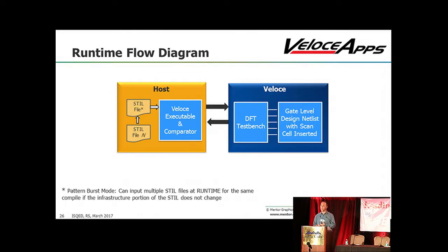You can run multiple patterns, just like you do on a tester. If you've got 100 patterns that all have the same timing and test header, your pin information, you can take all 100 of those and just run them all at one time.